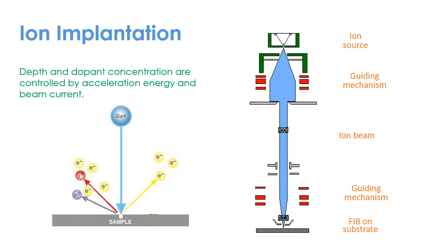The complete implantation operation must be performed in vacuum, so that the concentration of the ion implantation will be better. The high velocity impact of ions on the silicon surface will damage the lattice structure and result in lower electron mobility.